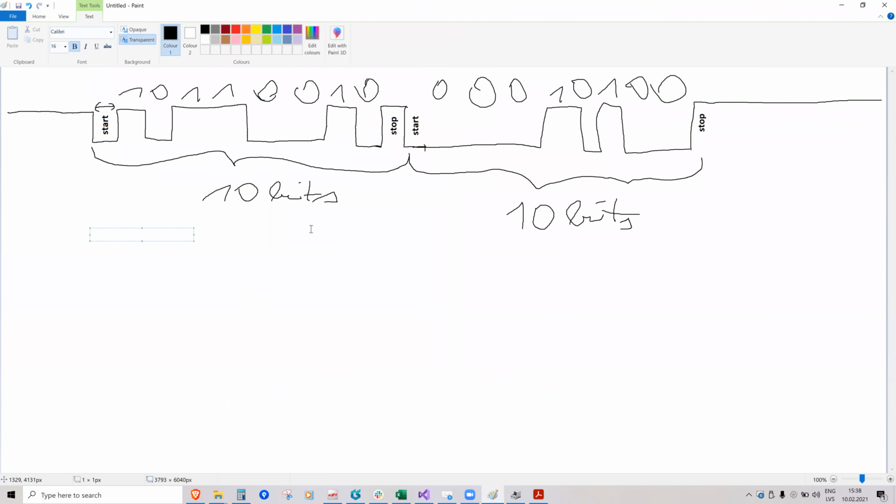One of the initial baud rates was 9600 bauds per second. And as I said, bauds include the start and stop bit, and maybe also the parity bit if it is used. So let's assume that in our case, it's just the start and stop bit.